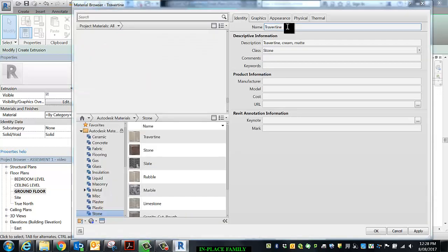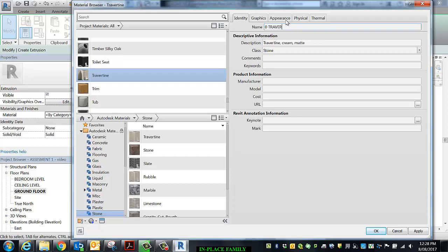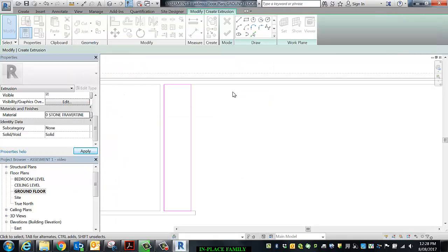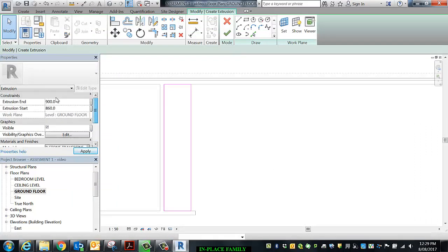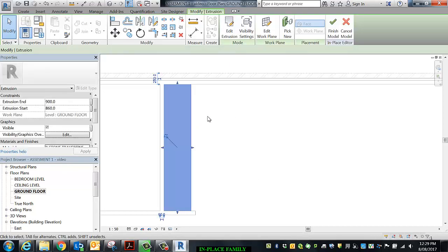Under identity, I'm going to rename it so that all the ones that I like to use are sitting at the top of the list. All right, so I've added my material. I will talk about materials later on, and there's also additional information on the YouTube channel that I've loaded, other videos called BD3D. Extrusion end was 900, extrusion start 860, and I've nominated a material. I hit the green tick to finish my extrusion.